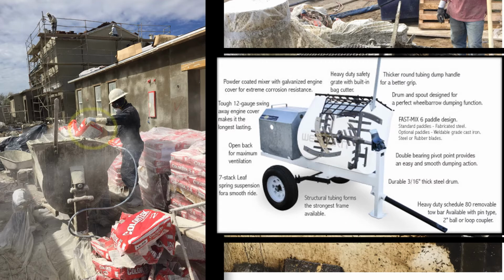Never remove the safety grid or put your hands into the mixing bowl while the mixer is running. It is possible the corner of the bag could be caught by the turning blades. It is important that you understand that losing a finger or hand is not worth grabbing that piece of paper from the mixer while it's turning.